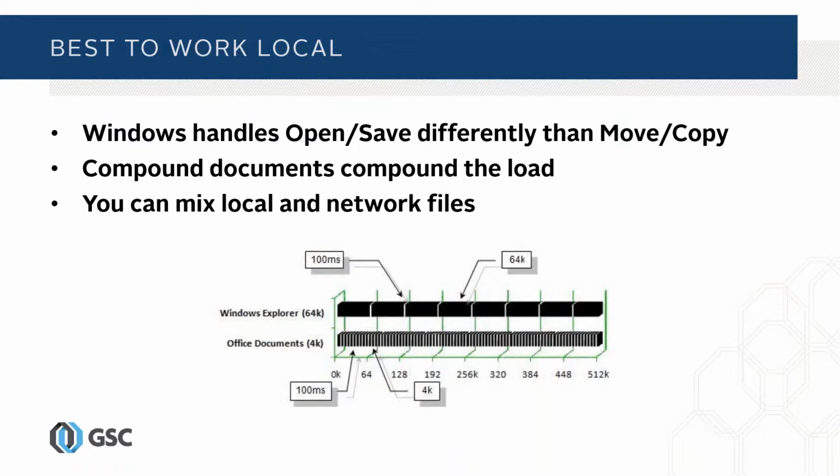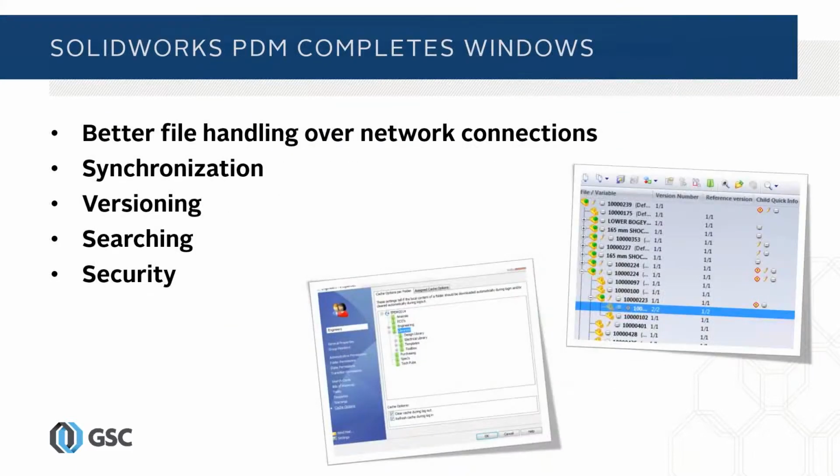Now, that's a pretty arduous manual process to do unless you have something that's going to do it for you, which is where SOLIDWORKS PDM comes in. Even PDM Standard does this. Because if you're in SOLIDWORKS PDM and you say check out an assembly, the first thing it's going to do behind the scenes is basically copy the assembly and all the related files from the network vault folder to your local hard drive in what we call the local vault view.